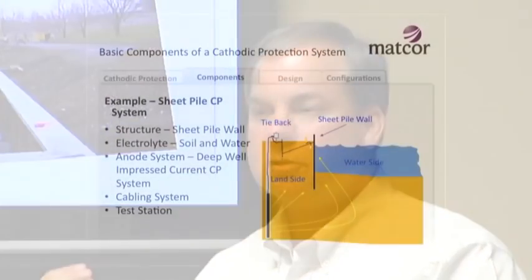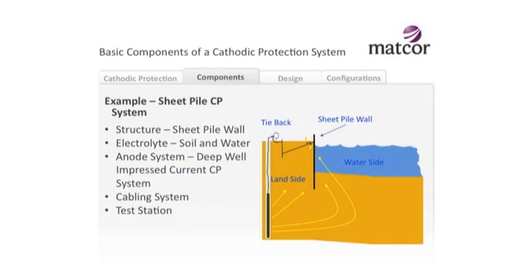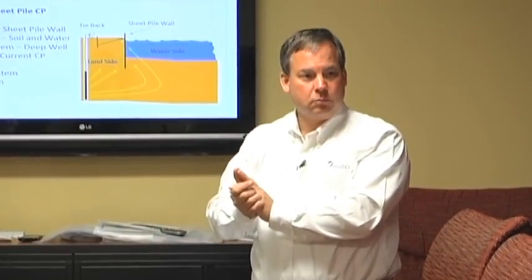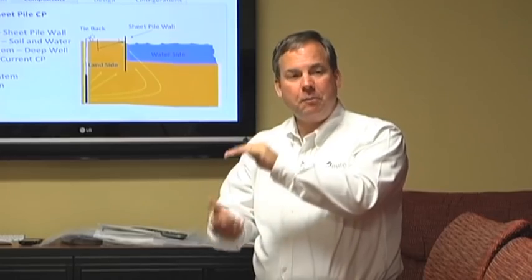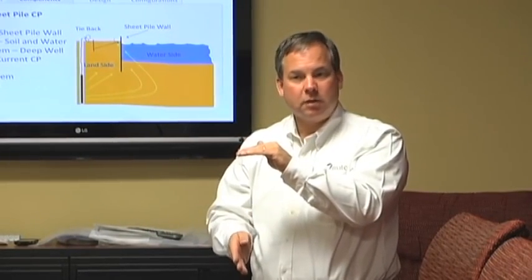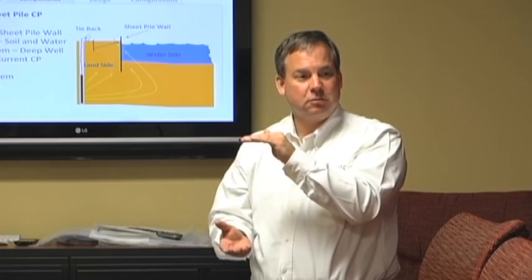Okay? You could also paint that. But the bigger concern for this structure is what's happening in the soil side and what's happening where it's buried and in the water. We've got this seawall structure, okay? There's actually a couple of places we're concerned about. There's the land side of the seawall where the sheet pile is driven into the land and you have soil side corrosion, okay? There's the very bottom of the sheet pile, which is in soil on both sides because it's below the water level. And then there's that area where the water is, okay?